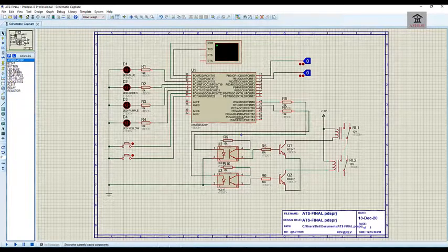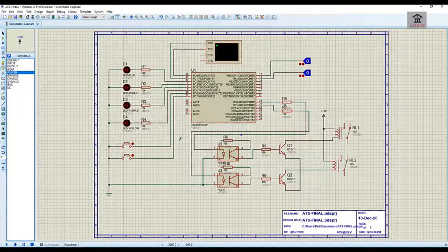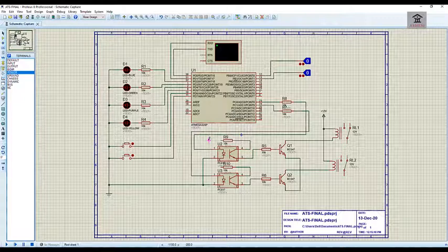After that, I'll go back to the power rail and then connect the power pin, which is the 5 volt or VCC, to these two resistors here, like this, and then like that. And then I'll connect this one to the power, this one to the power as well.